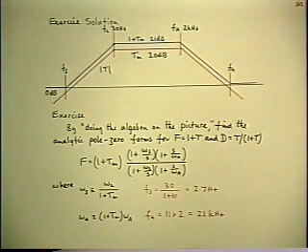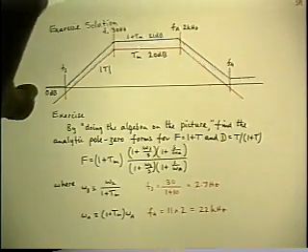So that's pretty straightforward. I kept emphasizing in anticipation of this particular problem that getting this result by the graphical construction is much easier than doing it algebraically when the T gets to be more complicated. Well, it's a little more complicated this time in the sense that T has two poles instead of the single one that we started with originally. So just to emphasize how much worse the algebra gets already for this case, let's see what would happen if you tried to find F algebraically.